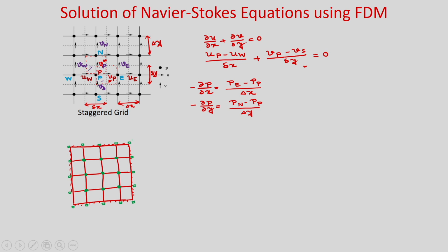So, if you see in terms of i, j, how many i vary for pressure, i varies here 1, 2, 3, 4, 5. So, 1 and 5 are boundary points, and interior points you have i equal to 2 to 4, because at these points you will solve. So, these are 2 to 4. Now, this is for pressure.